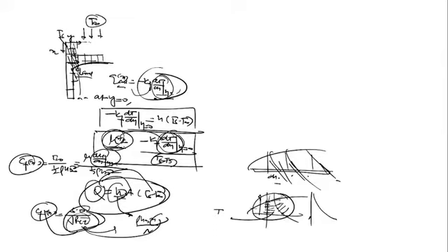So the concept of heat transfer coefficient is important to find the rate of heat transfer in complex conditions where the flow profile is not well understood, where you are not able to find the temperature distribution, because this method you can only use when the temperature distribution is known to you. You can find the rate of heat transfer by this method when the temperature profile is known, but there are too many conditions where the flow is not well understood, because to find the temperature profile you must write the energy balance.